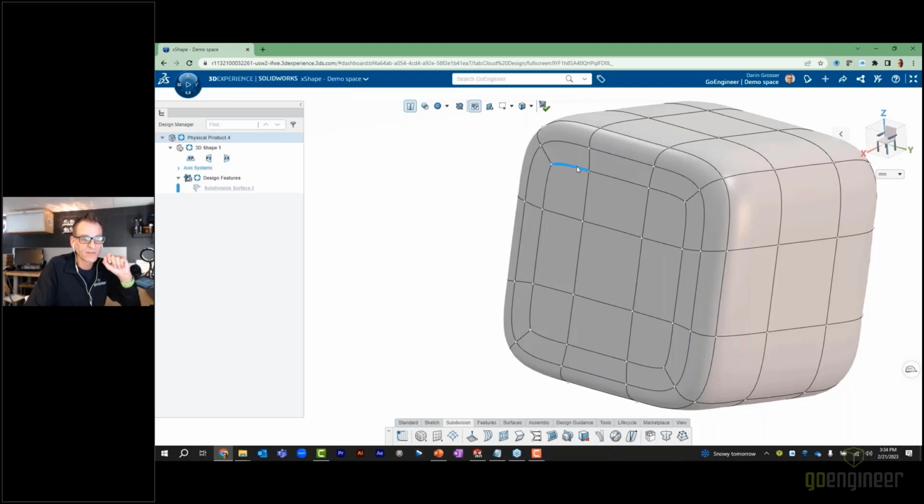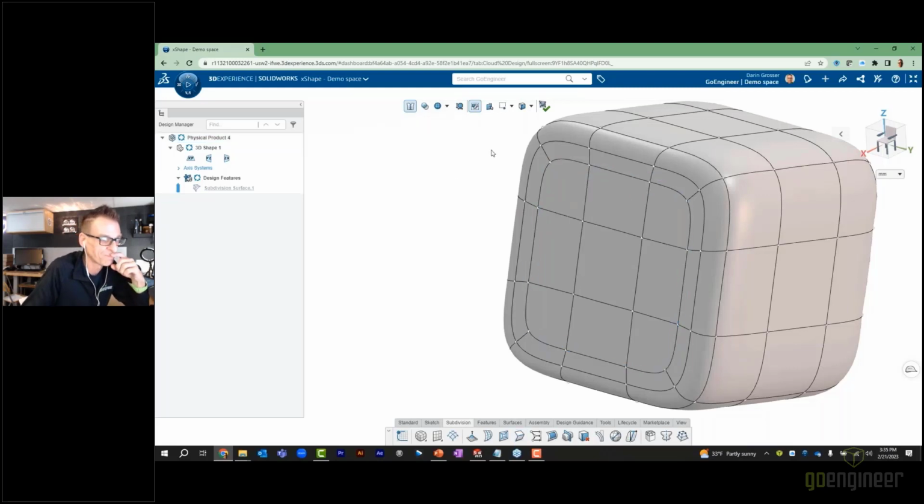I'm also going to double click this edge. It didn't select all the way around, but it looks like there's not quite a tangency in this corner, so I guess I understand. But if I use this shift when I pick on what is now going to be the south side of the midpoint, watch what happens. I'm going to hold shift, pick this edge, and it loops and picks the continuous or partial loop select, as we call it in SolidWorks, all the way around. So once again, pick one edge. I'm going to pick shift on the south side of midpoint, so that indicates the direction. And when I pick that edge, that's the direction it goes. Pretty sweet. Let's make a crease there as well.